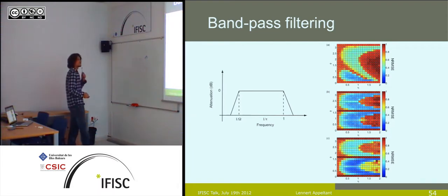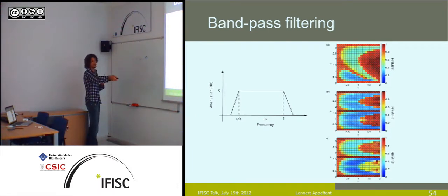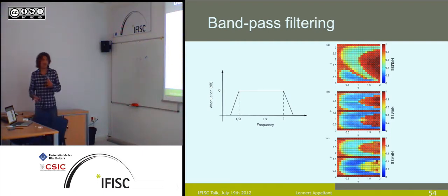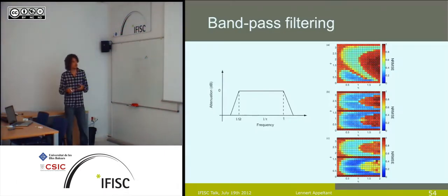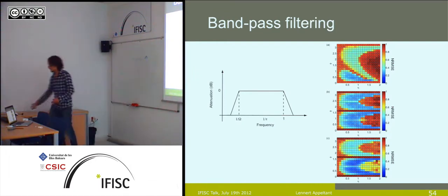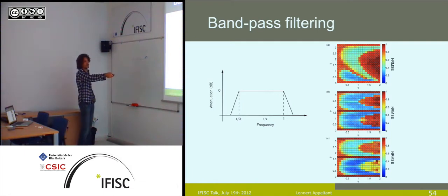Now, if we introduce bandpass filtering, as we do in these two plots, we eliminate the non-zero steady state. And in fact, what we see is that the performance becomes dependent just on the shape of the nonlinear transfer function, which is a sine square, which is symmetrical. And this is what we see also here in these curves. So you see the positive slope and the negative slope.